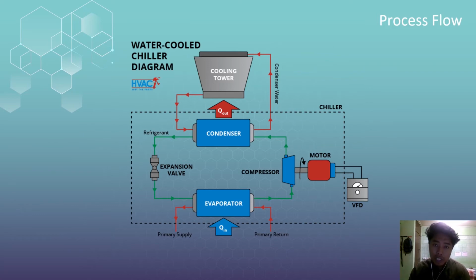The evaporator section of a water chiller is a shell and tube, refrigerant to water heat exchanger. Depending on the chiller's design, either the refrigerant or the water is contained within the tube. In a flooded shell and tube evaporator, cool liquid refrigerant at low pressure enters the distribution system inside the shell and moves uniformly over the tubes, absorbing heat from the warmer water that flows through the tubes.